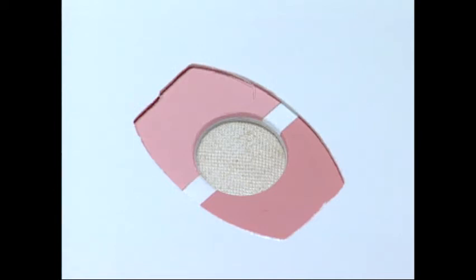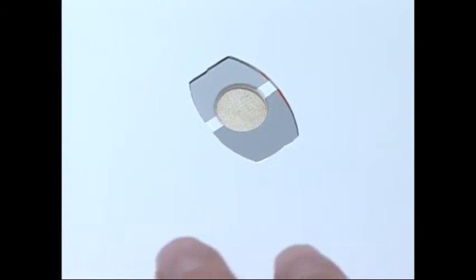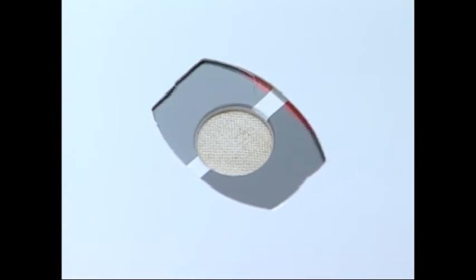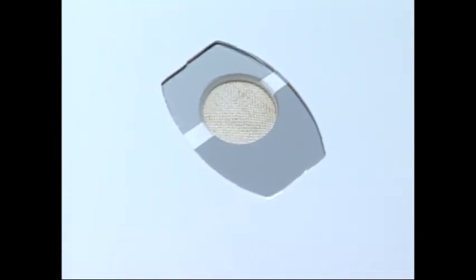Here, the red tile for rating between the 1.5 and 2.0 values is observed. Often a comparison of the level of staining on the gray column of tiles is beneficial, as the color of the stain does not always have the same cast as the tiles. Here, the wet crock stain is compared to the grayscale to confirm the rating. The actual rating would be done vertically.